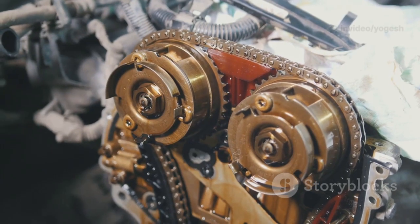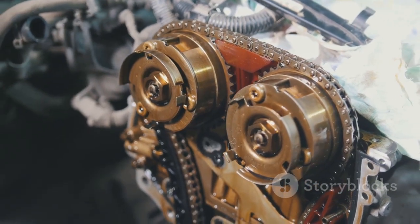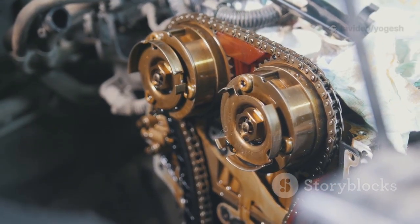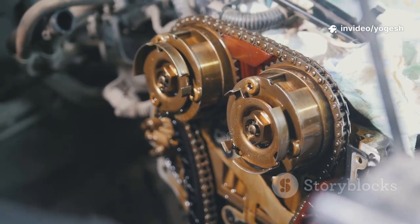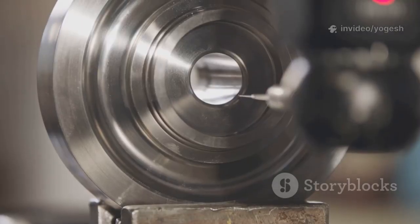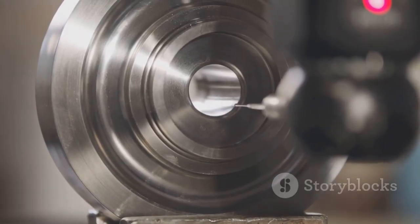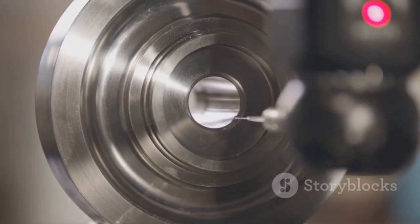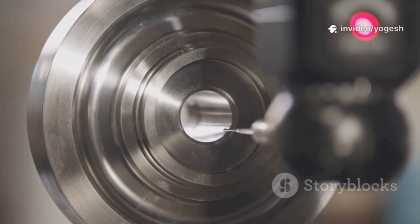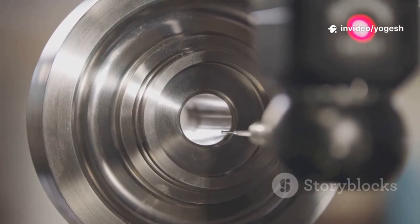Be sure to specify all the belt and chain details in the BOM, including their sizes, materials, and any special features. This ensures that when it's time to assemble, you have exactly what you need. Include precise dimensions for fixed center distances between shafts and pulleys. Accurate measurements are essential for smooth operation and to prevent unnecessary wear on the components.